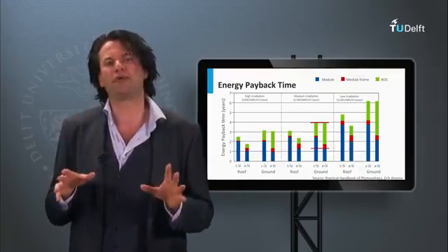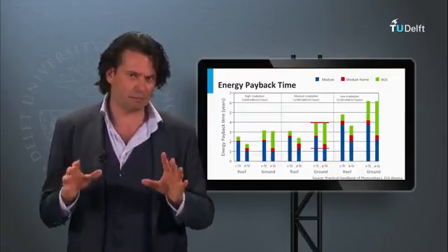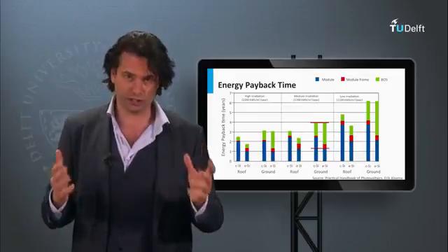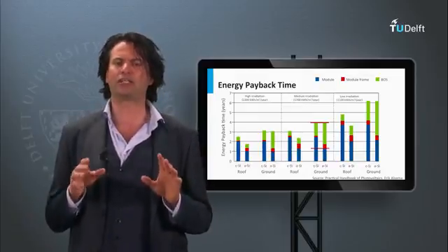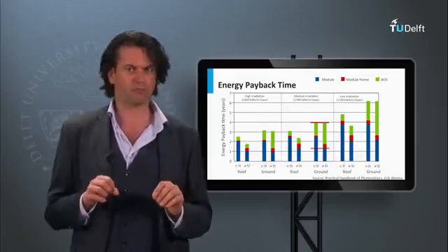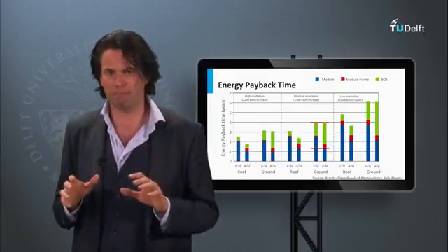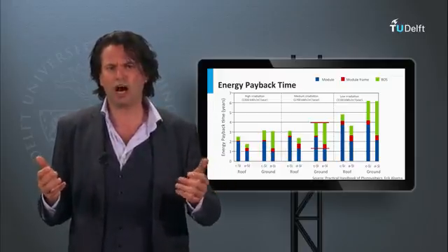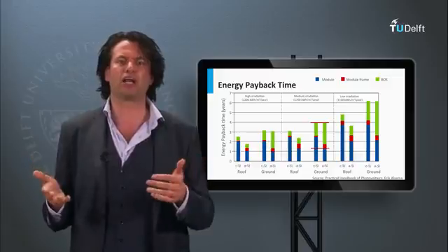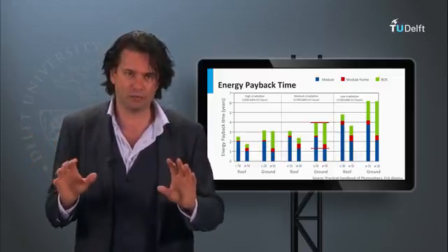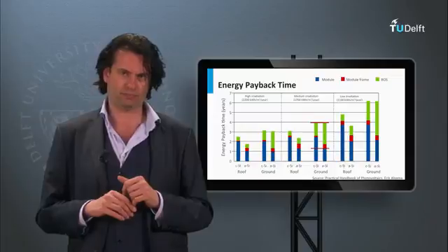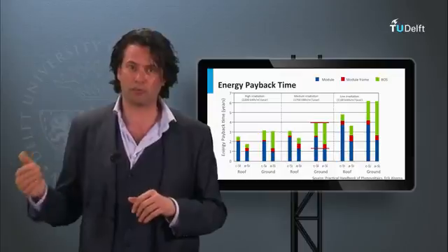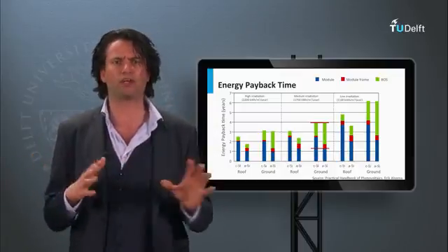I would like to remind you again that these fascinating differences in PV technologies can also affect the design choices at the system level, just like we had seen in week 7 in the modules block. The thin film amorphous silicon panels can work better under diffuse light. The crystalline silicon panels are more efficient, but the amorphous silicon panels are less power intensive while manufacturing. So we see again that a lot of optimization is required at the system level to choose the optimal module depending on several factors.